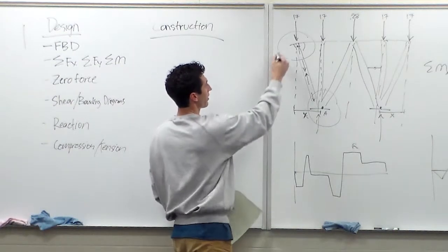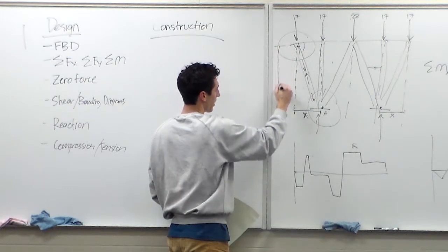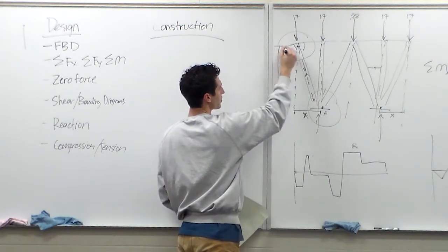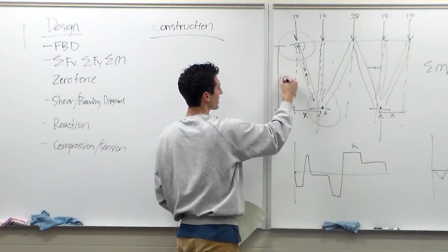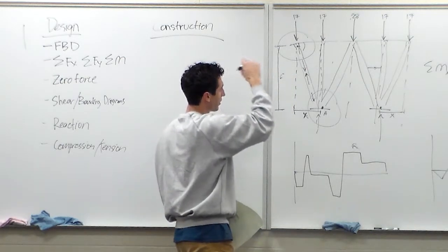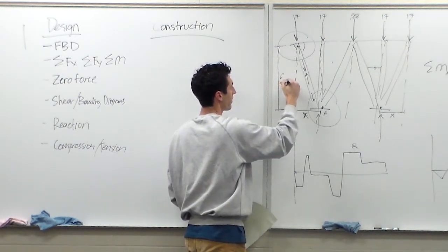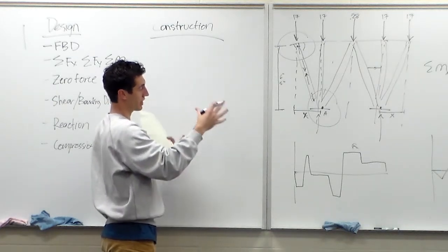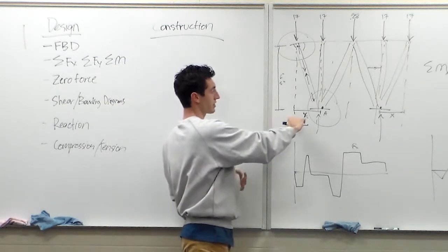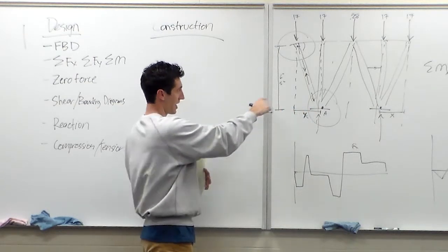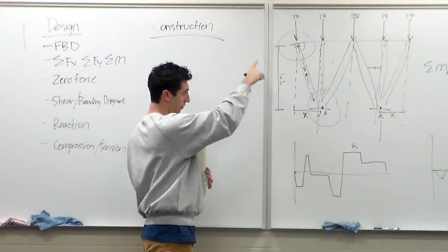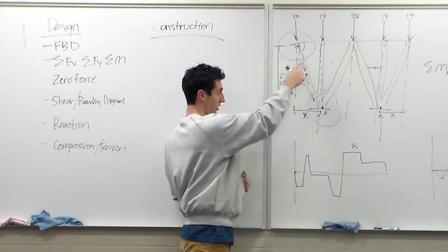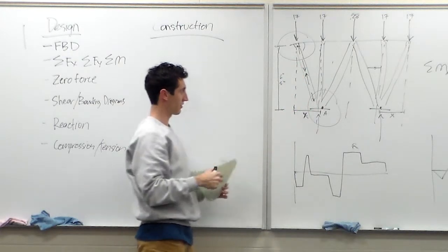Another little secret here is the maximum height. The rules will say, but I think it has to be less than 6 inches, but greater than 5 inches. So the height's going to change your length, it's going to change the way your moments work, it's going to change the distance. And so choosing a height is the first step, and then calculating your angles and then your moments and your distances and stuff like that.